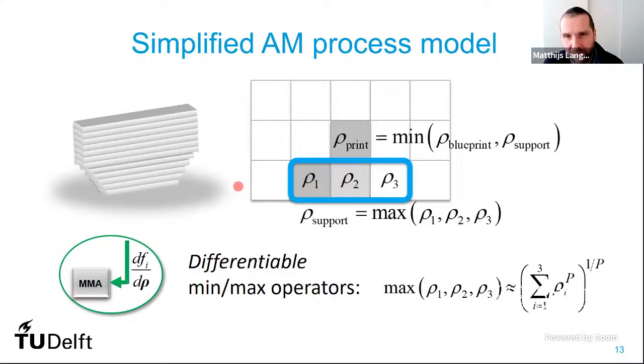And also here, the overhang angle is tied to the mesh, because here I have a regular mesh with square elements, which means that I get nicely a 45-degree angle in the results, which happens to be the angle that technology can still print at this moment. But maybe in some years you want to have a different angle, and then you actually have to. Okay, so the two things are related.